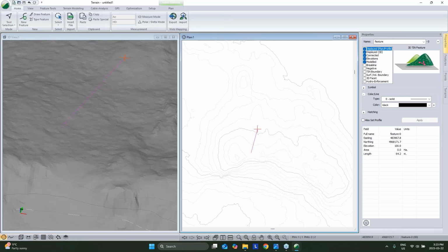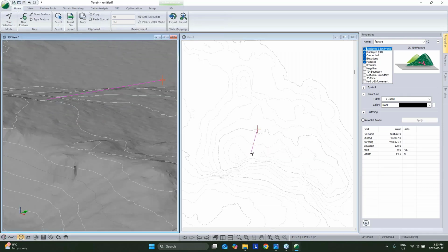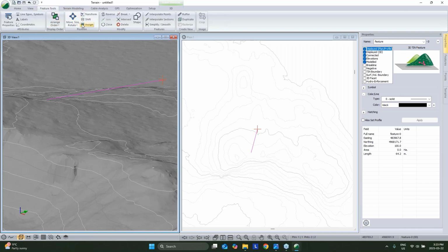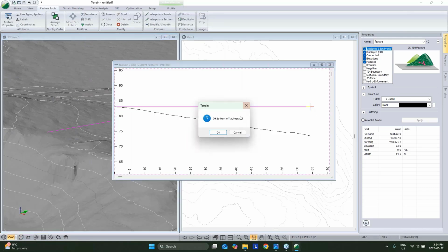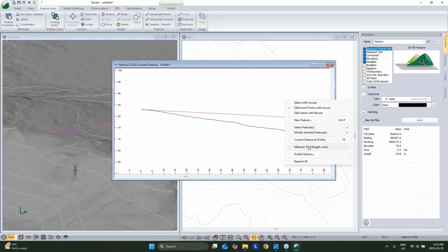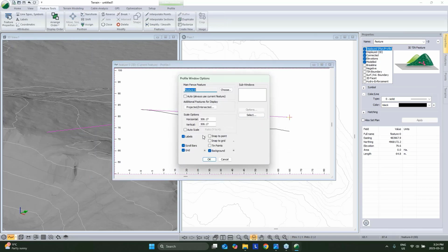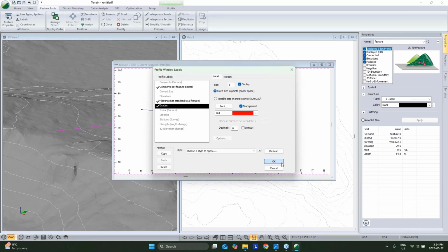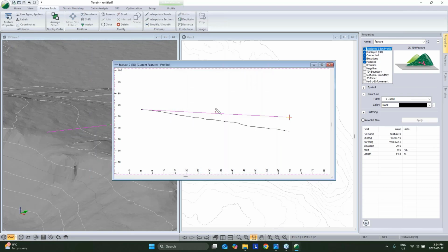And extending out, I'll usually shift that down to be in the right ballpark for my elevation. So I'll shift this down to be 83-ish. And if I want to choose the grade manually here, I could click my profile button, and I could grab this guy and shift it down. And if we want to see our grade, we can turn on our grade when we do that.